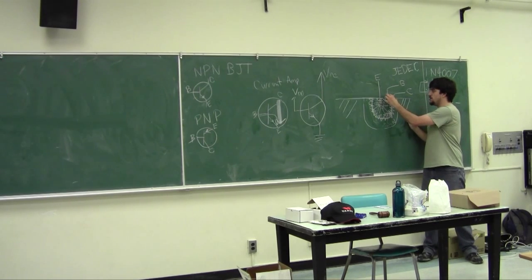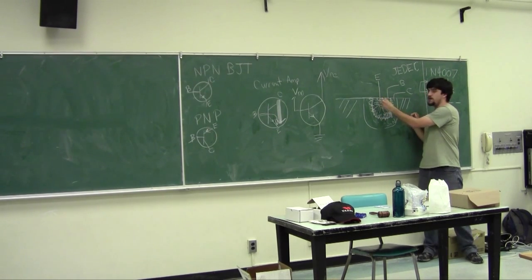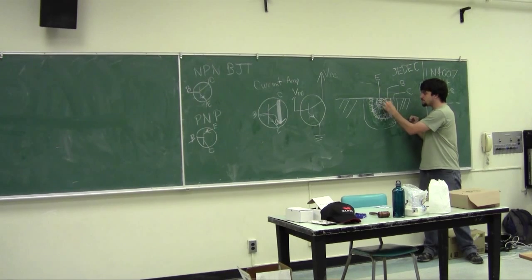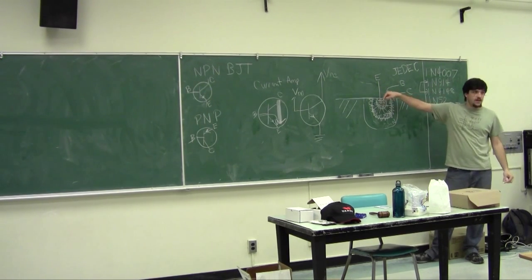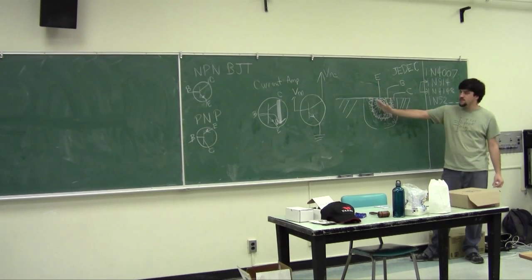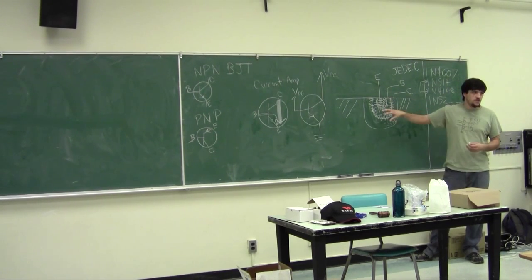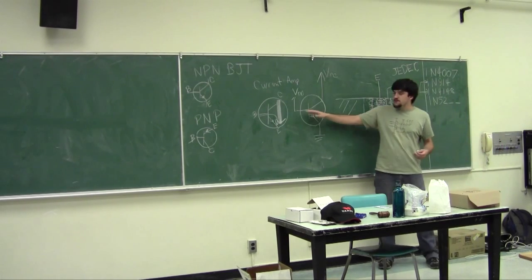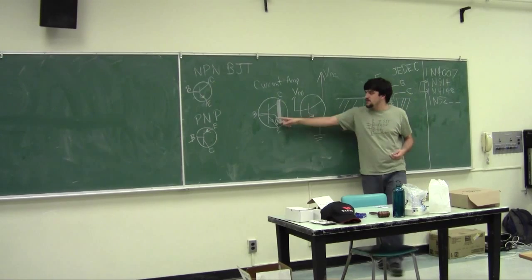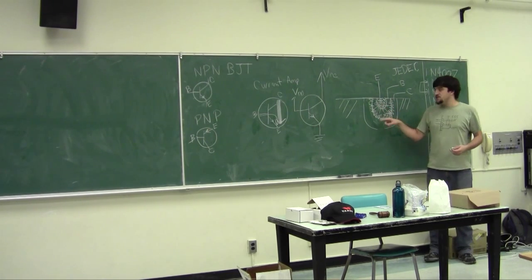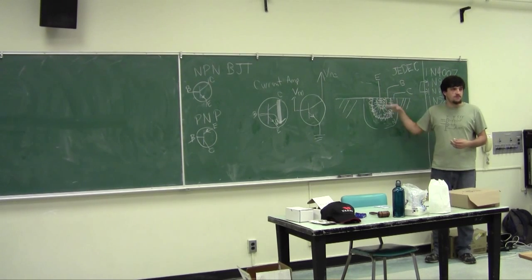This shooting of electrons is in almost no way related to base current, except that this collector emitter current depends on the base emitter current to continue to cancel out this depletion region here. Right? Because as you have negative charges flying randomly through this P section in the middle, you will inevitably get rid of this depletion region because you're having positive and negative charges cancel each other out. So you're going to recreate the depletion region, it's going to stop. So that's why it's characterized as a gain. Small current from the base to emitter gets rid of this depletion region and maintains the removal of this depletion region, and then a relatively large current flows through.